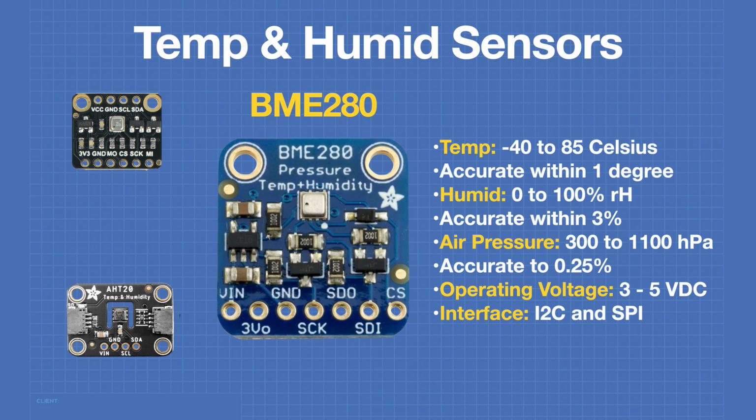The BME280 has very similar specifications to the BME680. It also can operate on 3 to 5 volts DC and has interfaces for I2C and SPI. Note that the interfaces share the same pins, and so you'll have to observe that during the wiring.